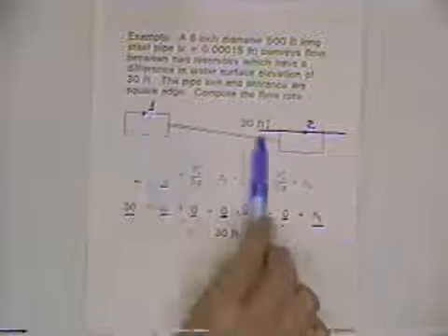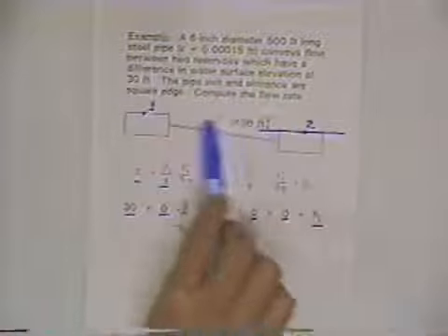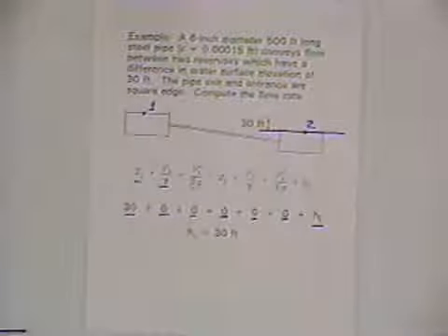In the classic problem that crops up quite frequently of connecting two containers of a liquid with a pipe, the head loss is always going to be the difference in the surface of the liquid in the two containers. And the energy equation does that for you and shows you that that's the case.